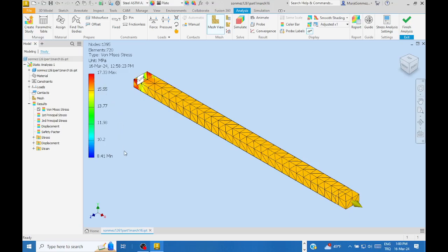The other technique is factor of safety. Okay? If you do not know or remember the yield limit for this material, then have a look at the factor of safety. In some countries, where people never obey the rules enacted by engineers and designers, and arbitrarily use the products in an overloaded manner, the factor of safety may be selected as maximum 5.